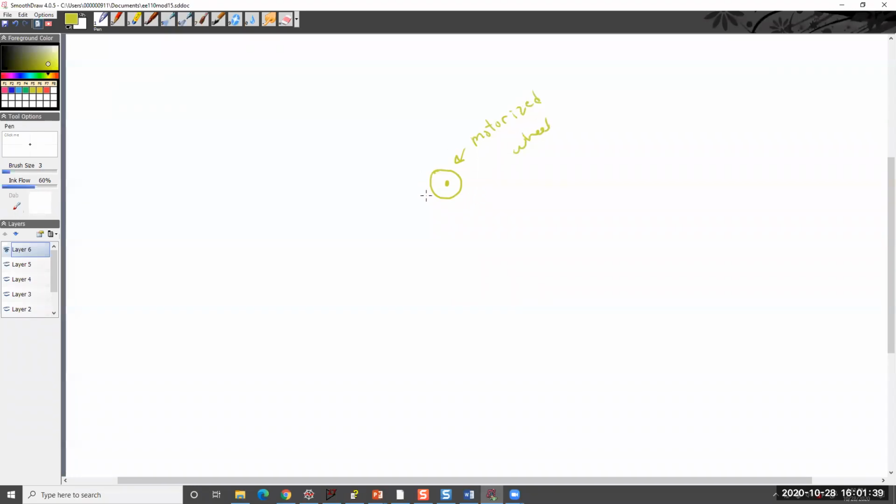Let's call this a motorized wheel, right? And my step response, I have 0 to 1 into that system. What I can have, like the speed, is related to the frequency of rotation. And so if I'm plotting omega, meaning how fast this is spinning up, I could put in a step response, the motor spins up and then hits some constant value.